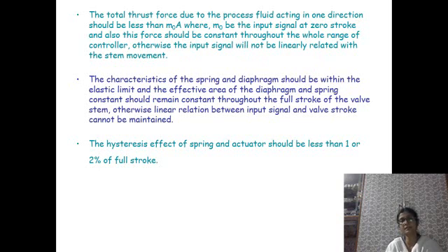Otherwise, the input signal will not be linearly related with the stem movement. That is another important aspect: the stem movement and the input signal should be linearly related. Otherwise, if the operation is in the non-linear region, it will not satisfy the control valve movement